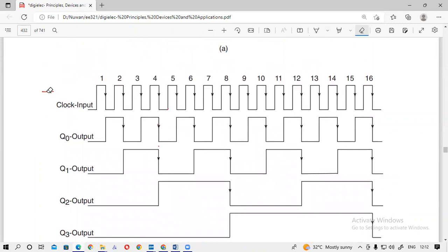So I think it is clear because you can see that the first flip-flop will shift a little. When it goes to the second one, this propagation delay will be double, so it will shift double, if we assume that all flip-flops have the same propagation delay.